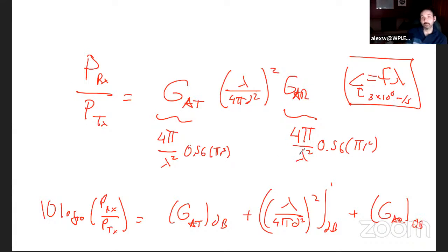Now, you can go even more crazy. First of all, what happens with an exponential? Now that becomes a product. If you divide something, it's minus. If you multiply something, it's plus. So you could stretch this out and put everything in decimal value. For instance, if I give you a class test question, and I say I want this answer in dB, here are the gain terms. Usually when we refer to gains, those are already in dB. So I'll say, here are the gains in dB. It doesn't make sense to convert them into linear, only to convert them back into logarithmic. But you're going to have to do the rest of these things.